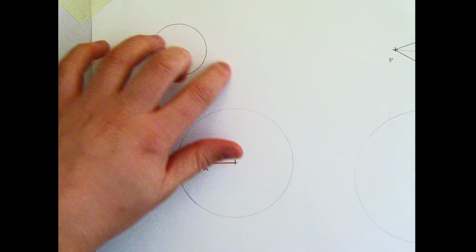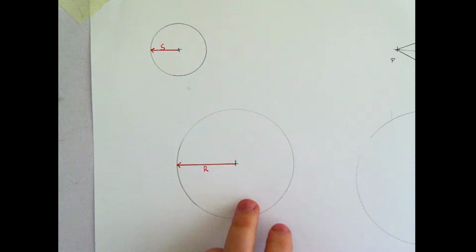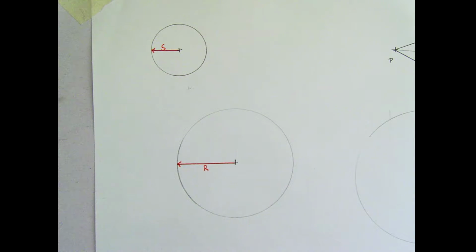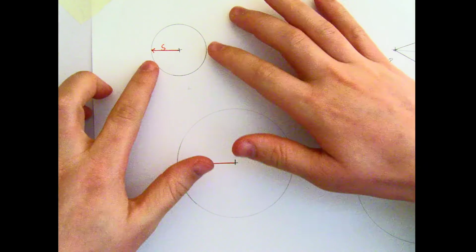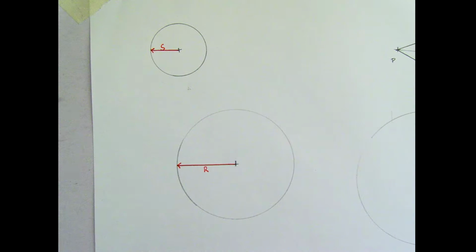This is external. So what we need to do here is we cannot draw a tangent between two circles at this point. What we need to do is reduce down the size of these into something that we can do. In a previous video I showed how to draw a tangent to a circle from a point that's not on the circle. So we know how to do that, and we're going to apply that information here to solve this question. If I take my large circle and my small one, how can I turn one of them into a point, into something that I do know? If I can turn one of these into a point and a circle, I can solve this question.